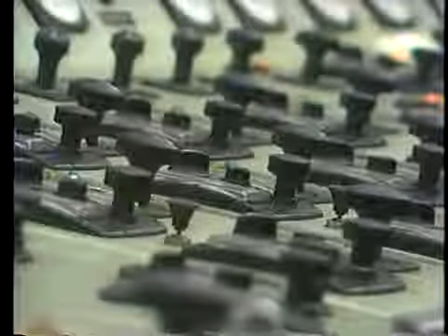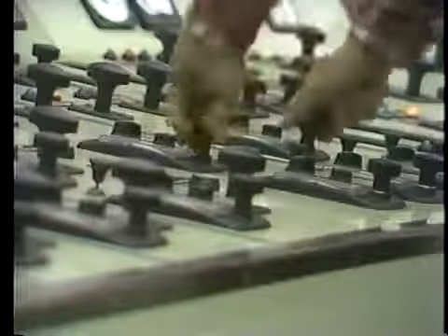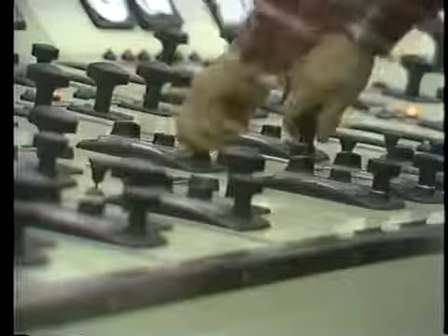Generally, an operator has several indications that make it possible to verify that a flame is present in the boiler. Viewing ports, mirrors, and television monitors allow visual indication that combustion is taking place. Typically, if an operator discovers that the boiler flame has gone out, procedures indicate to immediately shut off the fuel supply and to purge the boiler for a designated amount of time before restarting the flame.